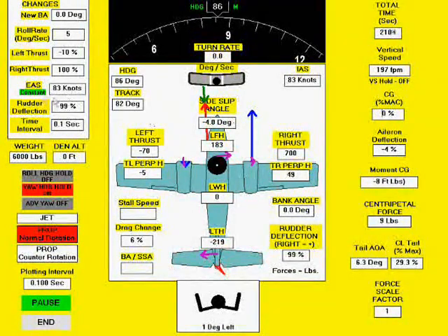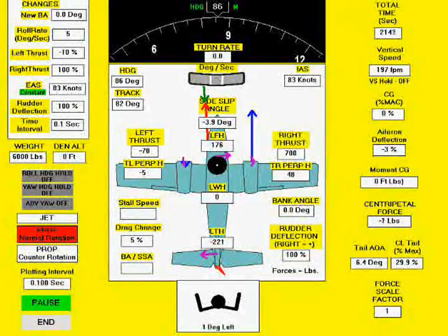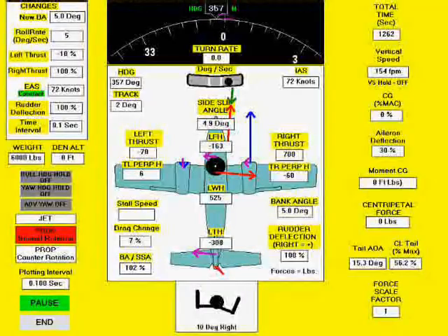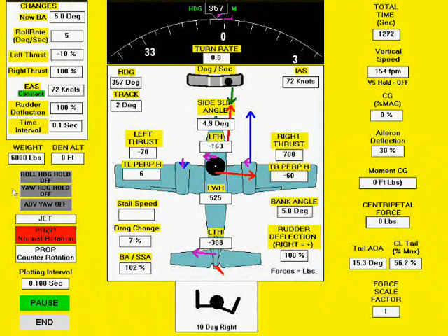The resulting change in VMC is less than 1 knot for the wings level value of VMC. Changing to the VMC at 5 degrees bank angle and 0% mean aerodynamic chord, we select the rear limit of 25%.